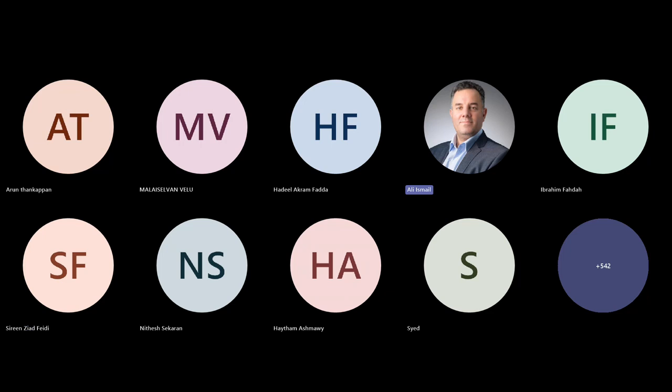The question from Muhammad Kashif is related to the shared parameter. I think this is something related to Revit and a very technical question. It is not necessary to use instance shared parameter. If you think you can make these parameters family or type, please go ahead. At the end, we only need to have the parameter attached to every door in your case. So do the best practice that you think is correct in your case, to avoid entering the same instance parameter many times.